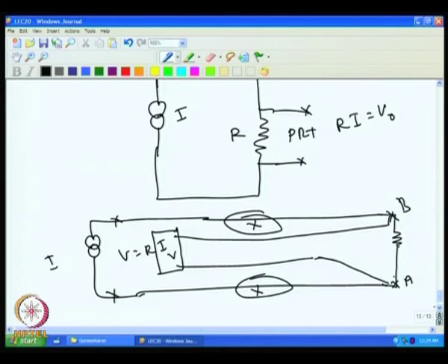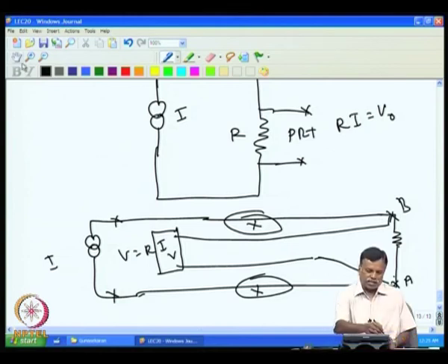Now, if you look at the current sources, we have different current sources that are used. We will quickly see what the different current sources available are and which one is suited. Now, one problem is whether this technique can be used for high resistance. For the medium range of resistance, this technique works well. For low resistance, very low resistance also, this technique works all right. In the medium range, we can also use a bridge if balancing is not an issue. But if it is a high value resistance, for example 100 megohm, then this technique is normally not favored, because of the following reason.